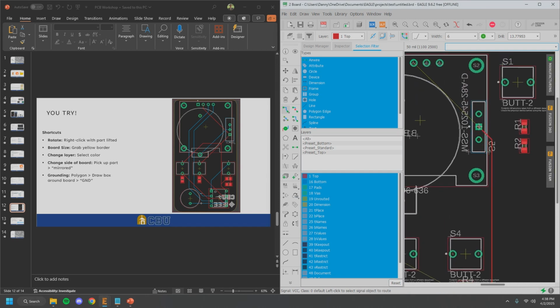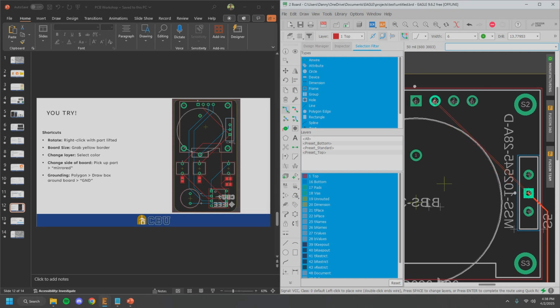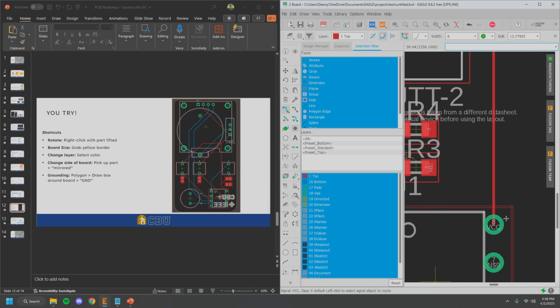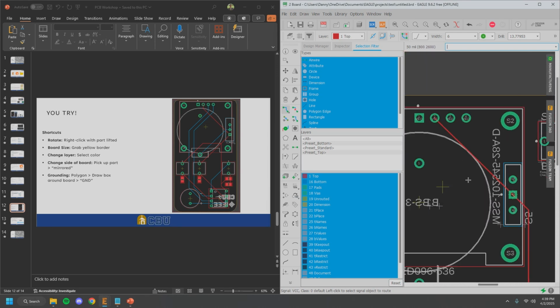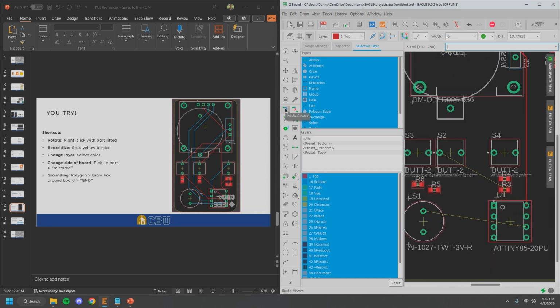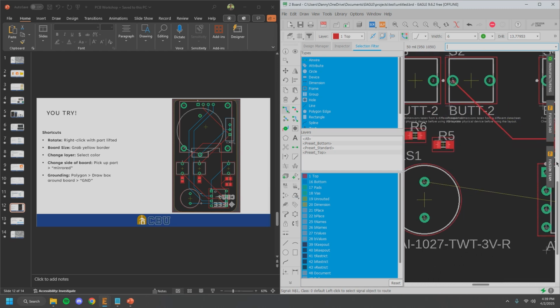But again, you're just declaring where everything is going to be manually, and there's no changing this after it's printed. So you can see there, with those two simple connections, I have now given power to these different components, or I have wired them all together. And so what you want to explain to students is that using Route Air Wire, you're just going to connect everything that is declared that needs to be connected.